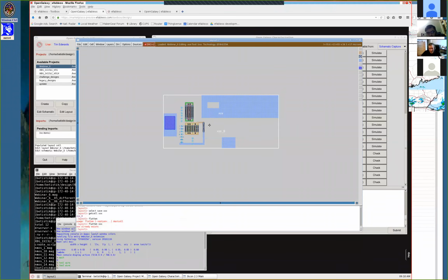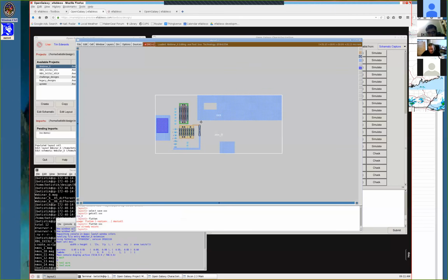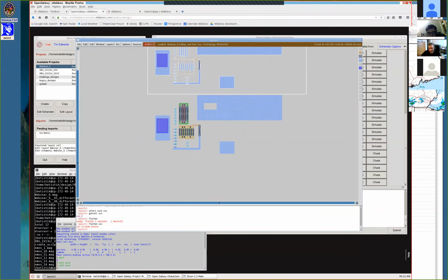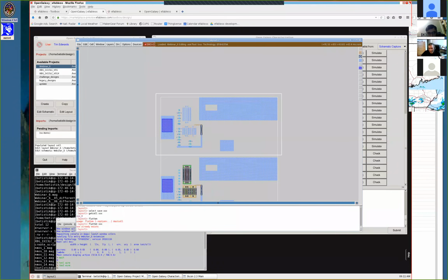But if you just want to flatten what's in it, you can do this, which is, again, to go Control, which gets rid of the whole cell. Select everything in it, and for instance, C for copy. All right, now I've just copied not the cell itself, but everything in it. This is still a cell down here, but I've just taken all that paint and made a copy of it in a flattened sense. Yes.